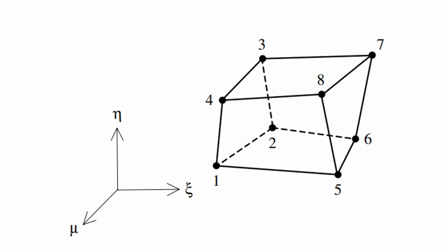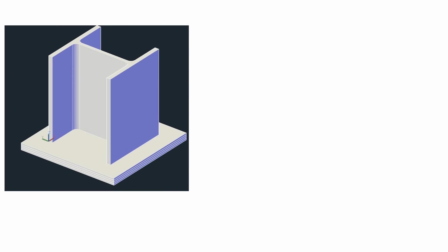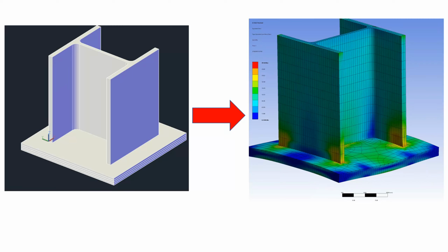Finite element technology for 3D elements, such as brick elements, enables the structural engineer to analyze and design a small part of a structure, such as a structural steel connection. However, such 3D elements are not suitable for the structural design of buildings. Modeling all structural components in a building using 3D elements, such as brick elements, will cause a huge number of degrees of freedom, which will also demand huge computing power, and then lead to inefficient loss of cost and time.